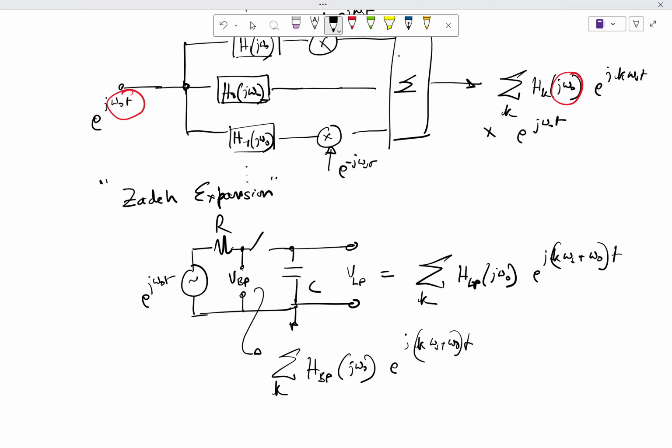And because the RC time constant is much, much larger than this on time, whatever voltage across the capacitor we are sampling persists throughout the cycle, right? Depending on off time, definitely it is going to persist. There is no leakage. In the on time also, there is no significant change in the value of the envelope, right?